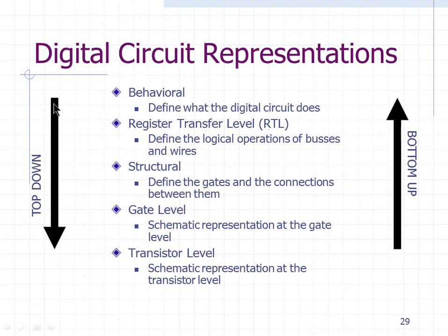We already saw this. One thing we will see in Verilog is that a digital logic circuit can be represented in these various formats. The bottommost format is the transistor level, which is CMOS level. So you can design your chip at a CMOS level and implement it. Or the structural and gate levels are combined. We call it structural level, where we create a structure of the design using basic gates and some other blocks, and we write Verilog code directly using those blocks and gates, with all the interconnections in between done manually in the Verilog language.